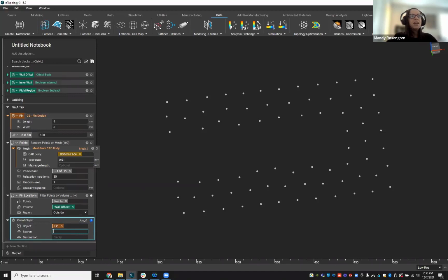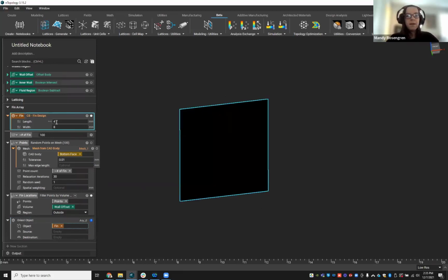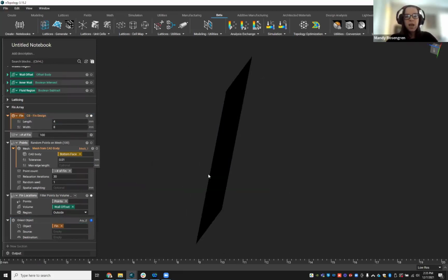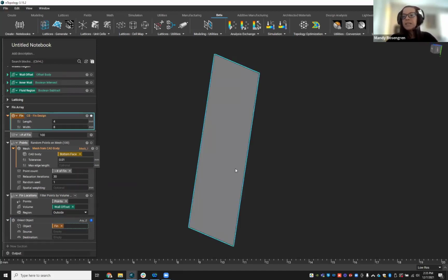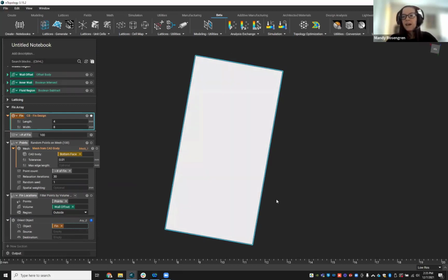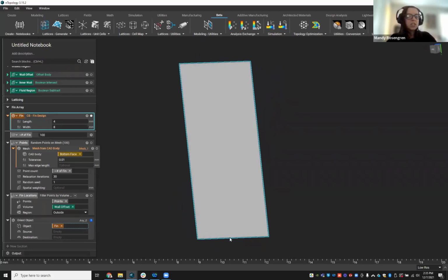Our source plane, if you look at our plane or our fin, I'll type a Z to focus on this. I want to place this onto all of those points so that it's in the center of that X and at the minimum point for that Y, and then it can just be at that centroid for the Z. I mean, the Z would just be at that 0 location.